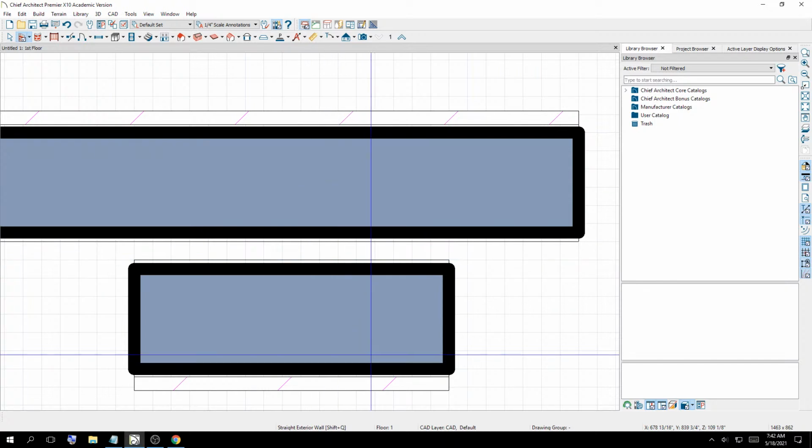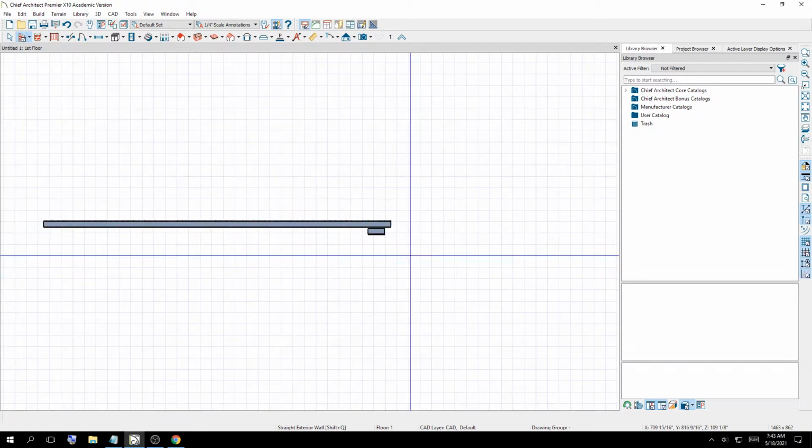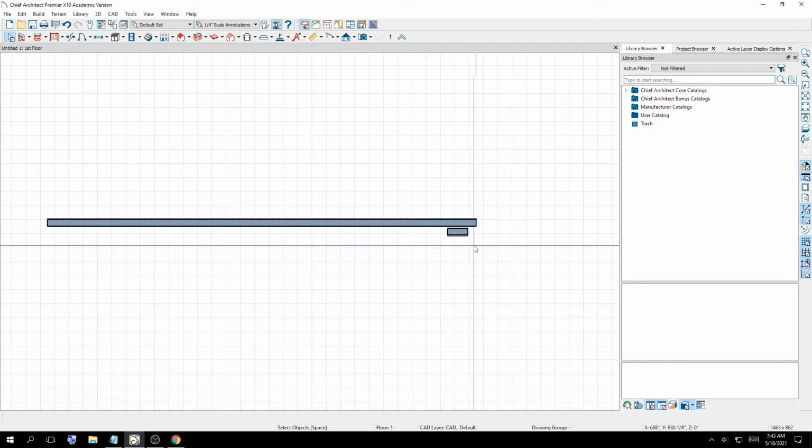but as you can see here, we have two walls. There's actually a different, almost like a candy striped horizontal bar here, and then there's one here. That is your outside exterior sheathing. That is the siding of your house. And then the wall framing members will be inside here. The black will represent the sheetrock that would go on top of the framing. Obviously the sheetrock on the inside of your house would be painted. There would be sheathing on the outside of your house, followed by some sort of house wrap and then a siding. And then there'd be insulation on the inside. So that's kind of what you're actually automatically given when you just create a simple wall.